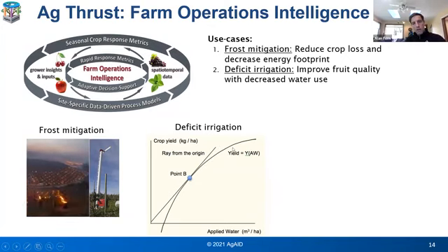And so what deficit irrigation is intending to do is, on one hand, you're just trying to save water, right? So there's a cost to the water that you have to use. And if there's diminishing returns, obviously you don't want to go out here somewhere because you'd be losing money, basically. But also with a lot of crops, crops like grapes, they literally like to make the grapes thirsty in some sense because it helps them produce sugar. It stresses them.